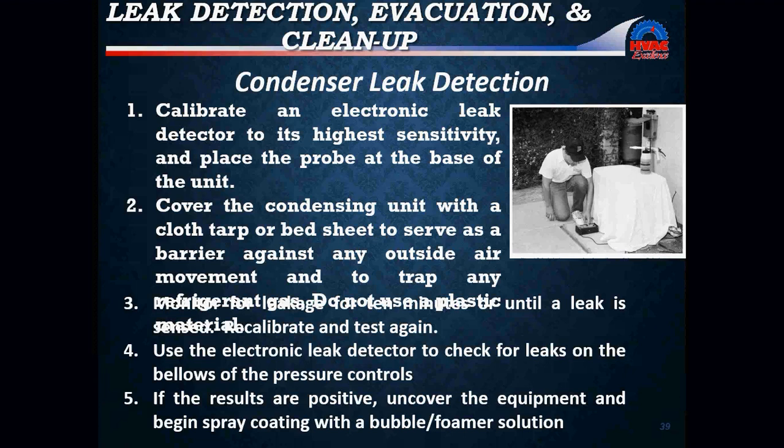But again, if you have 2 positive test results, chances are the condenser is leaking. Now you're going to want to move on and try to find and pinpoint the actual location of that leak. Where you're going to want to look is where your screws are, because sometimes some guys put in screws that are longer than they need to be because they lost one in the grass, and they puncture a hole in one of the U-bends on the end of the condenser.